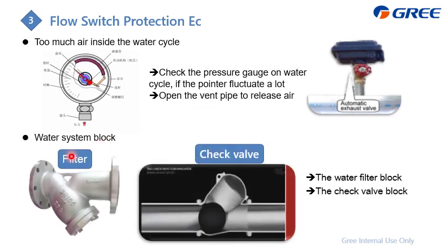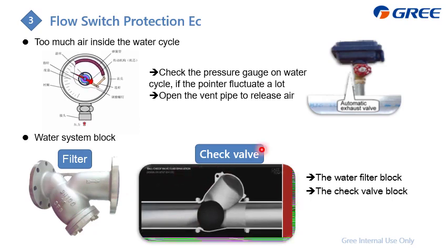And the next is water system blockage, including the filter and also the check valve. Maybe for this one, the inside coil has a malfunction, and as for the check valve, you also need to check whether it can conduct or not. And this is how the check valve operates.